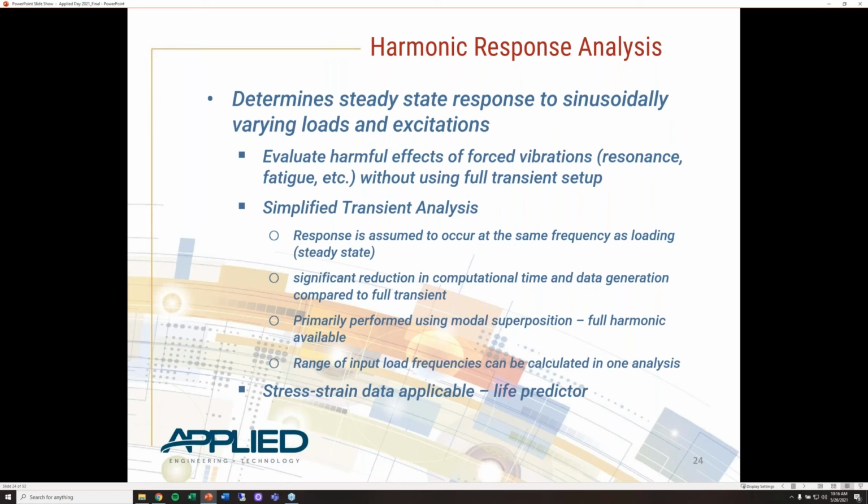So if that assumption is true, this analysis can be a great tool, a very computationally efficient tool, providing significant reduction in computational time and data generation compared to full transient analysis. And again, this is an extension of modal analysis. We will use modal superposition to perform this analysis.